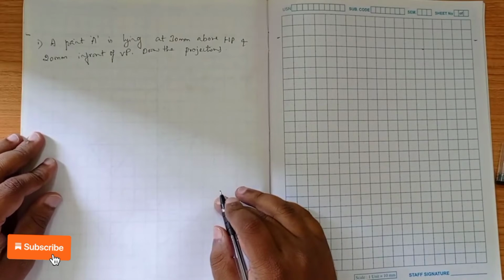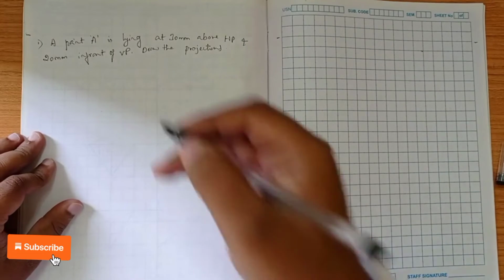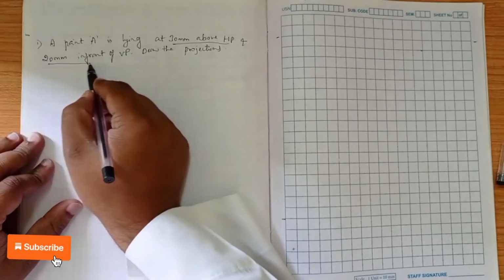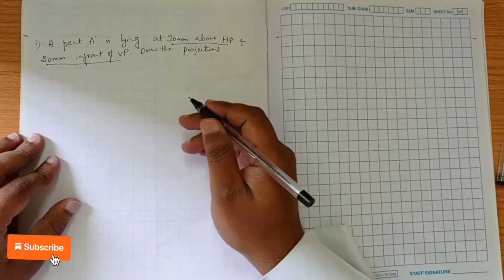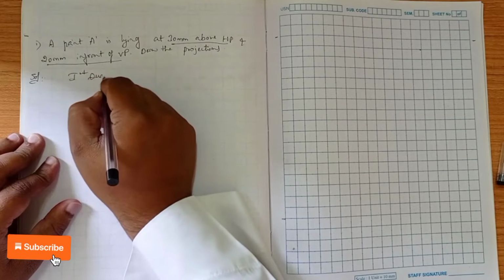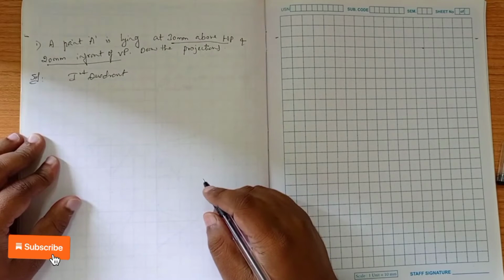So we have discussed there are three concepts in solving the projection of points. So first concept is to identify which quadrant. We know that if a point is lying 30 mm above HP and 20 mm in front of VP, that is above HP and in front of VP, it is in the first quadrant. Okay, so now we have identified the quadrant.